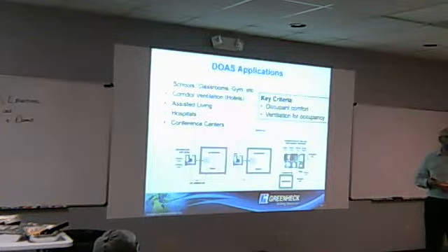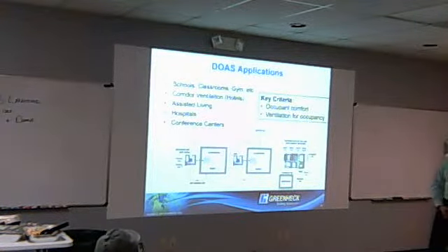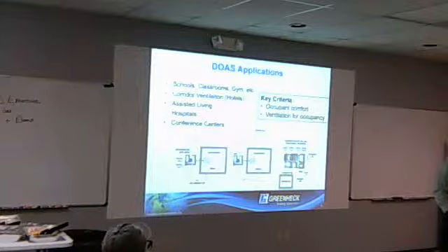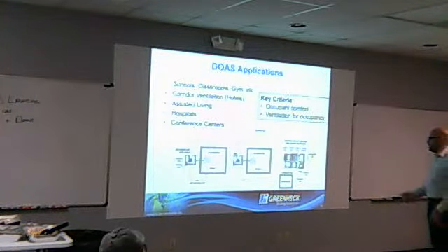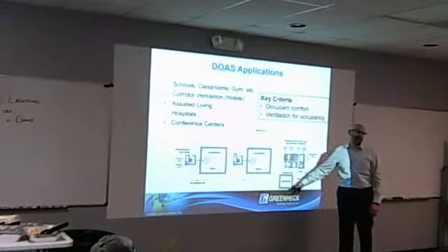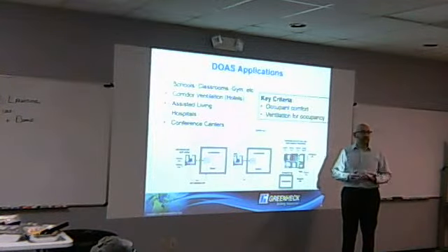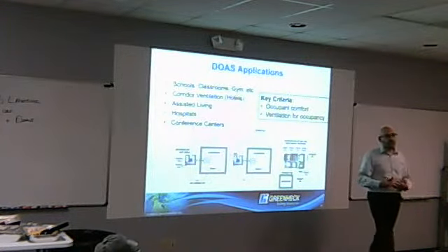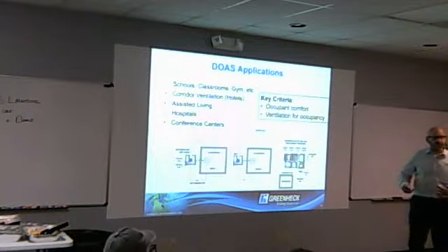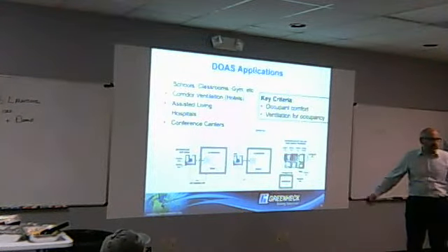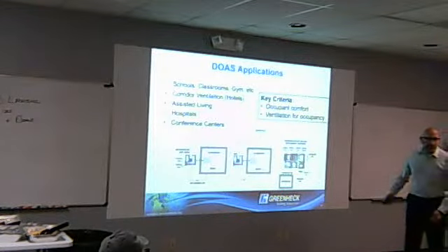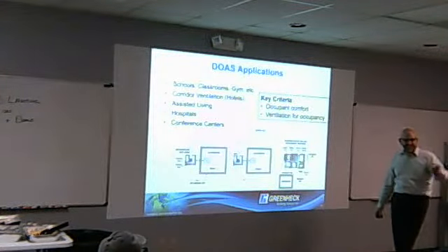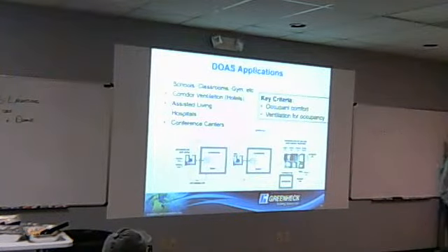So with that energy wheel, we are putting some of the restroom exhaust air back into the classroom. In a wheel, at most, you might have 1 to 3%. ASHRAE, like in other codes, allow up to 5%. So the air that you're taking from a space is in different classes. That'd be considered, I think it's class 2. Like above class 3 and 4, you don't want to recirculate, and that cross leakage is not acceptable. So we won't take that in. But like restroom exhaust, anywhere you think about your normal breathing, not that big a deal if a little bit leaks over. Well, like at the Wuhan lab, probably I don't think I'd use the wheel in that case.